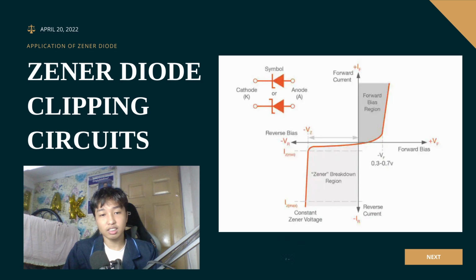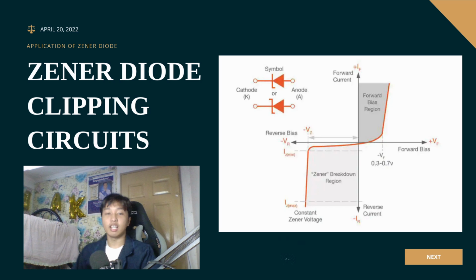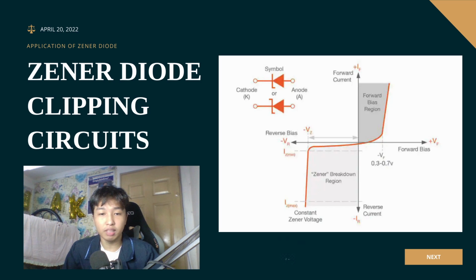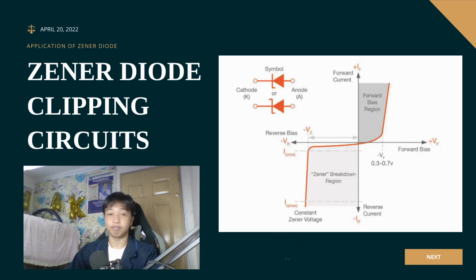Two biased clipping diodes are utilized if both the positive and negative half cycles have to be clipped. And the bias voltage does not have to be the same for both positive and negative diode clipping. As depicted, the positive bias voltage could be at one level such as 4 volts and the negative bias voltage at another level such as 6 volts.